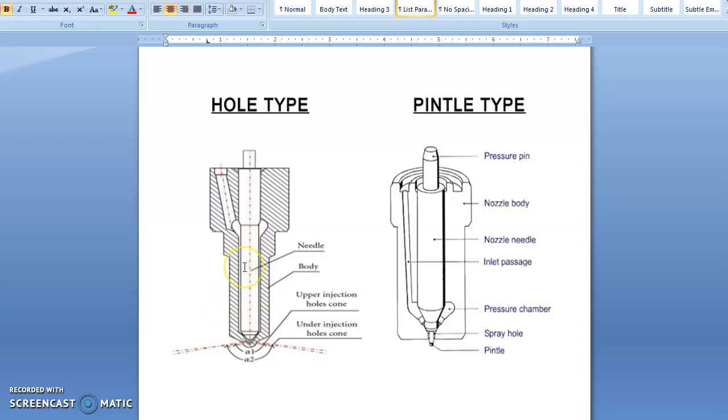So here is how the injection takes place. When the injector pressure falls below the spring pressure, the valve closes. This action tends to set up an oscillation of the valve during each injection and consequently breaks the fuel into small particles. As for fuel leakage, the fuel leaking past the needle valve stem enters the upper part of the injector and is returned to the pump suction chamber and the fuel tank.